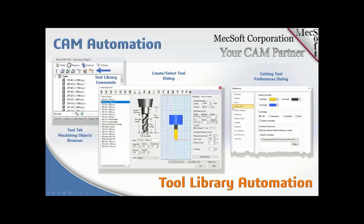When you define your tool, you're obviously going to set your tool dimensions, and you can set your feeds and speeds and the properties of the tool and some other options here. This knowledge gets saved with that tool based on the tool name, okay? So you can embed all this knowledge that you need for a certain tool, and then you can carry that knowledge over into your operations when you load that tool.